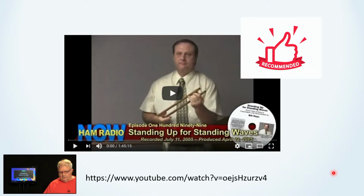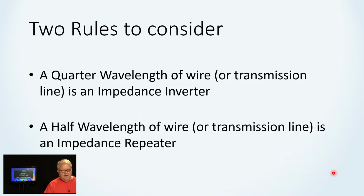Two things I want to pull from this presentation, two rules. A quarter wavelength long wire is what they call an impedance inverter. And a half wavelength piece of wire is an impedance repeater. You can watch the video and get more details on that. It has to do with how long your ground connection cable is.